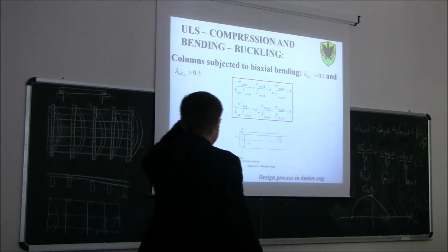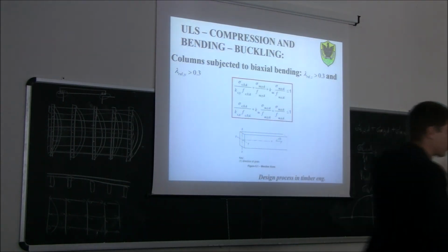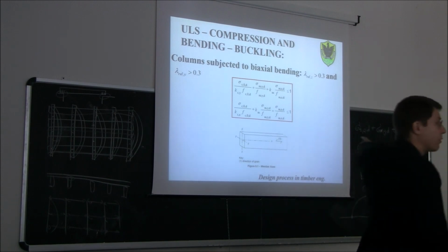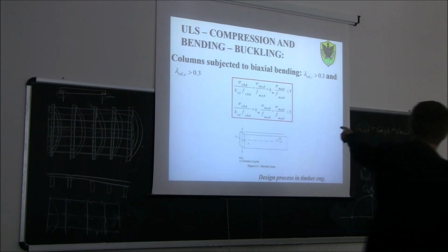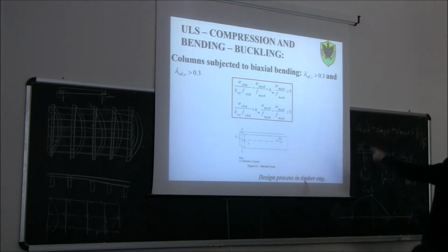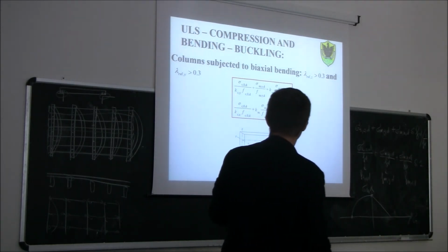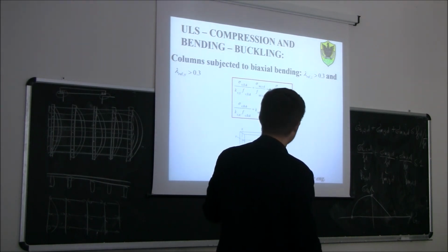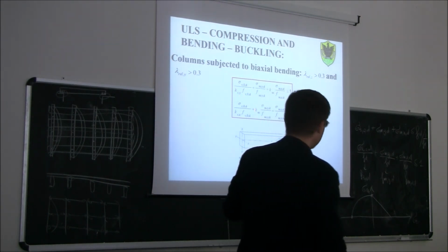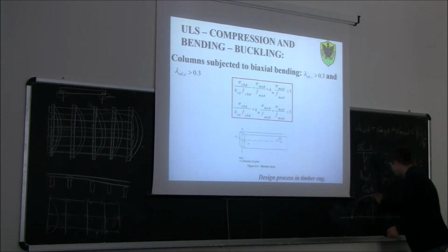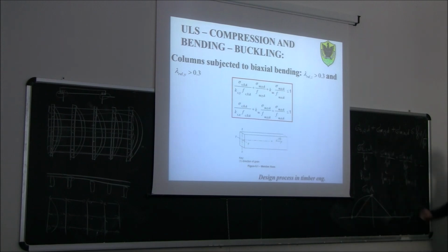Instead, if you have buckling, flexural buckling, because we are talking about form, you see again, we have a linear domain, where, however, on the denominator now, you need to put the reduced strength, the strength reduced due to buckling. You see there is a K, this reduction factor due to buckling times the strength. So in this case, the domain is something like this. So this is without buckling, and this is with buckling.